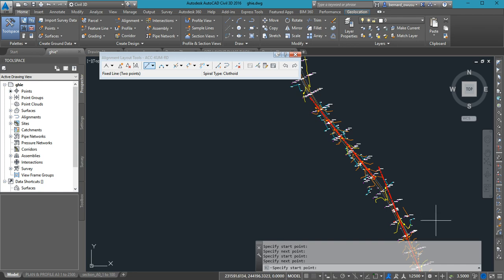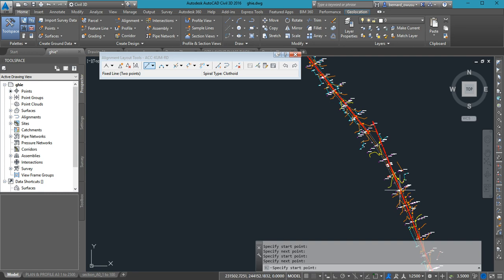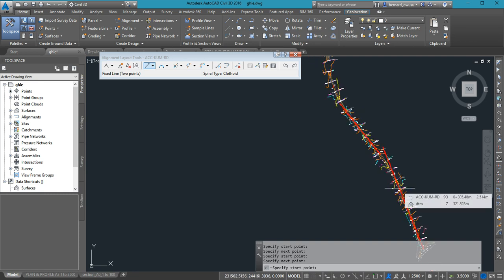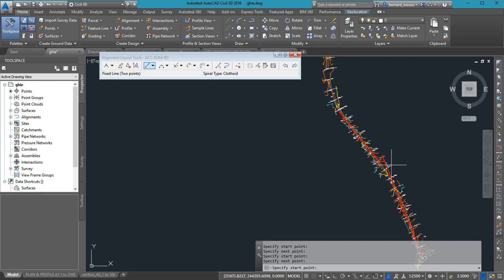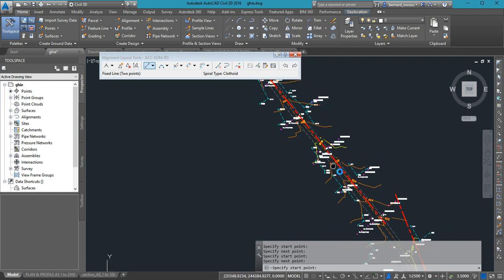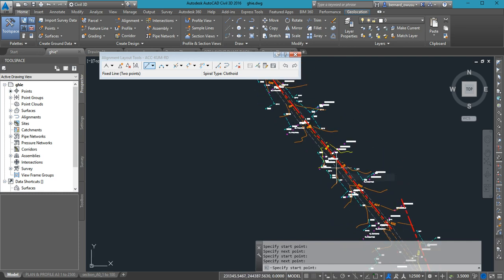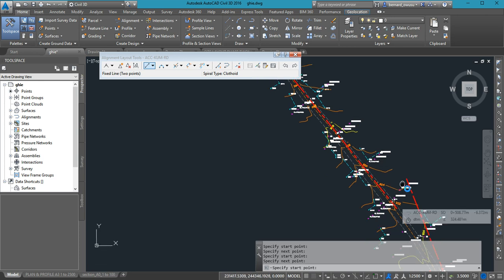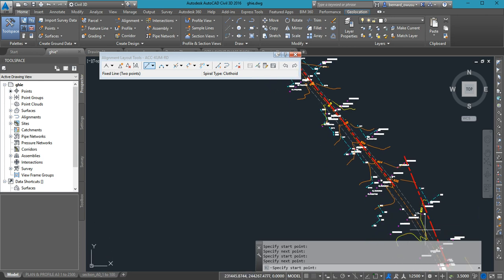Please watch what I've done. The one who is asking, should you start from where you ended? Please see, this one I ended here. You don't need to come and start from there. Just look at the existing road and draw your tangent. Forget about where the first one ended. It does not need to cross it. The most important thing is that the two are not parallel. Once they are not parallel, it means that when you extend, they will surely meet somewhere, and there will be an intersection point.